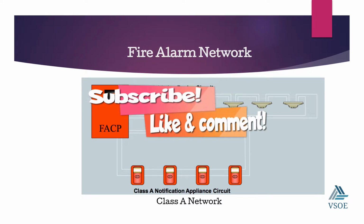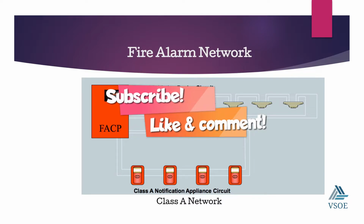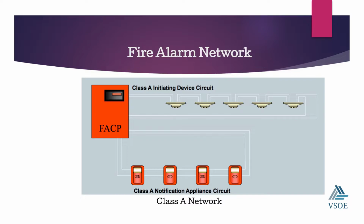So when we talk about the Class A network, look at the notification device where the circuit is fed from one device to another, then returns back to the panel, right? And then we have the same configuration layout for the notification devices, where the loop is taken from one device to another, then it goes back to the panel, all right? So there's multiple outputs for the notification devices, and there's multiple inputs for the notification devices.